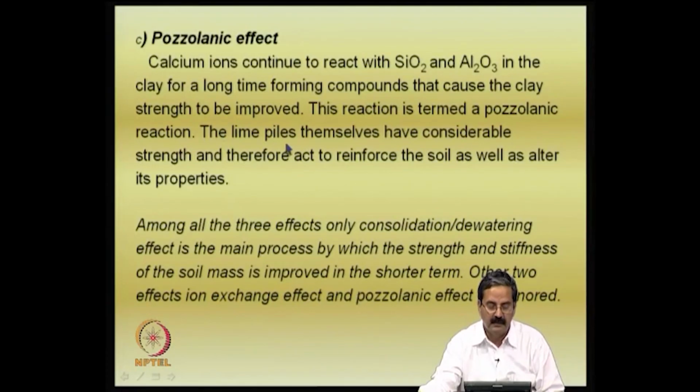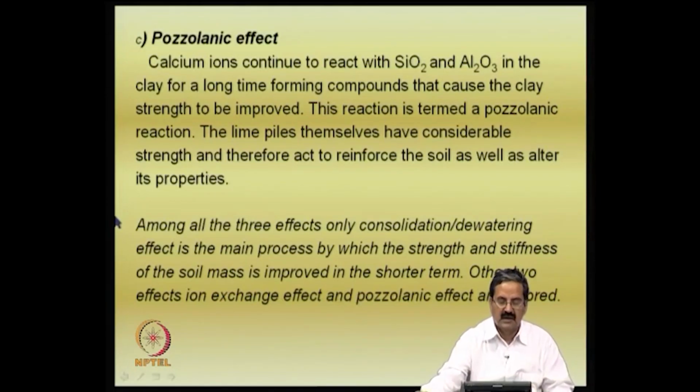Another important thing, the lime piles themselves have a considerable strength and therefore act to reinforce the soil as well as alter its properties. So, there are so many mechanisms that it has advantages, and it is also cost effective, very economical. Normally, if you want to design, we are essentially looking at the consolidation dewatering effect as the main process of strength gain, and I will just show you a design method of how it can be done. Okay.